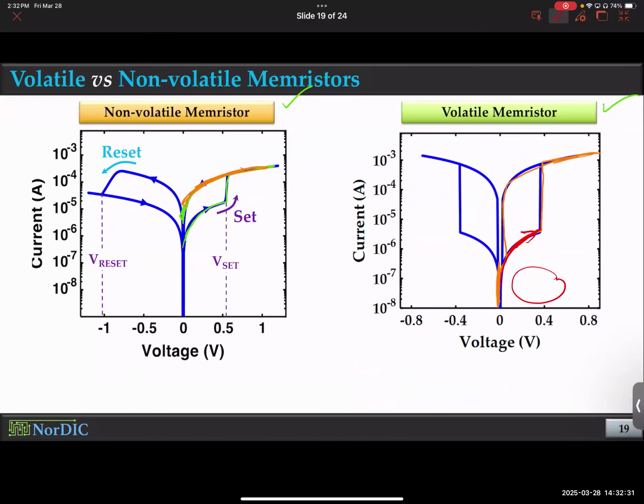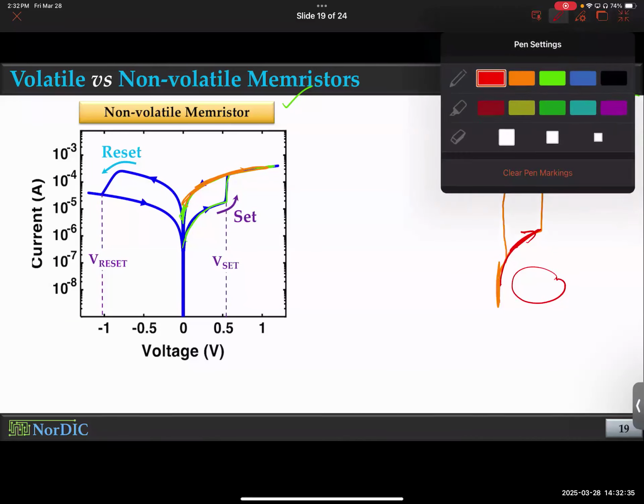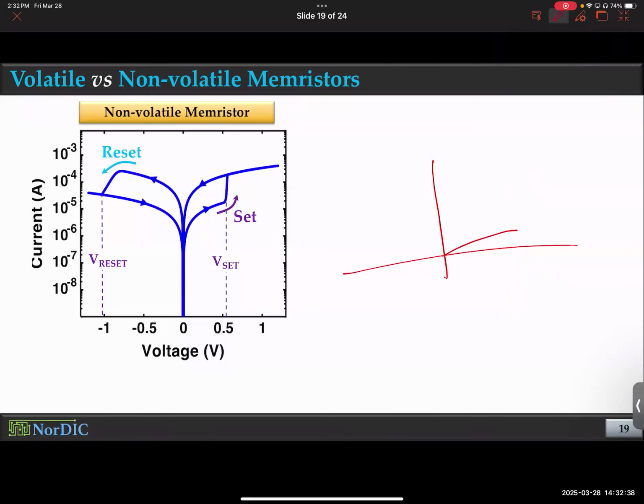And if you take a step back, don't look at this busy slide, maybe. Let me draw it for you. So you have insulator to metal transition here at this point. And then metal to insulator transition occurs at a different point, MIT. So you have two critical points, insulator to metal transition, metal to insulator transition. Notice both transitions occur within the same polarity. You don't have to go to the other polarity. Does that make sense, folks? You see the uniqueness here?